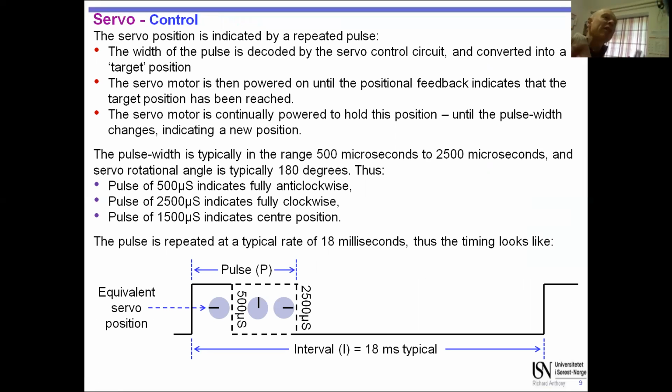Servos are designed, there's a kind of industry standard. Every one I've used in the last, I don't know how many years, but it's definitely more than 20, every single one of them has conformed to a range of between about 16 milliseconds to about 19 or 20 milliseconds, and 18. In fact, I think the actual recommended standard is something like 18.2 milliseconds, right? But as long as it's between about 16 and 20, it works.